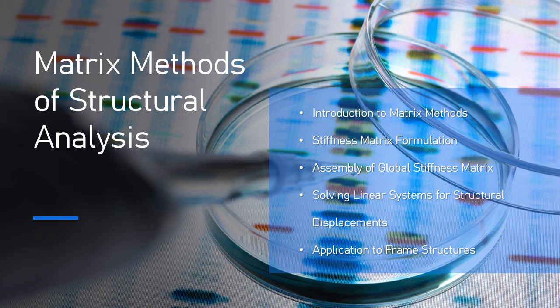1. Stiffness matrix for 1D truss element. A 1D truss element is the simplest structural element. It has only axial stiffness and no bending or shear stiffness. The stiffness matrix for a 2-node truss element, with axial deformation, is derived from the relationship between the axial force and axial displacement.